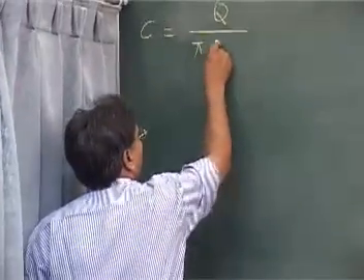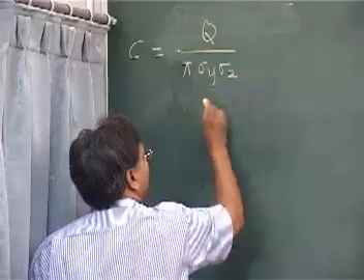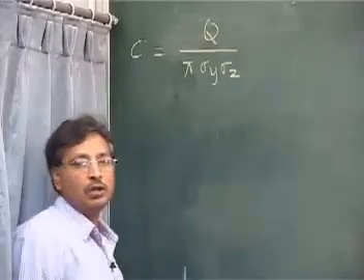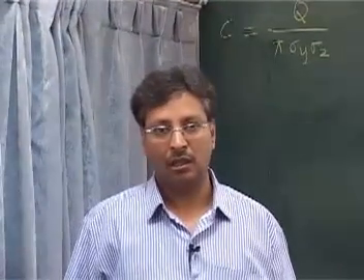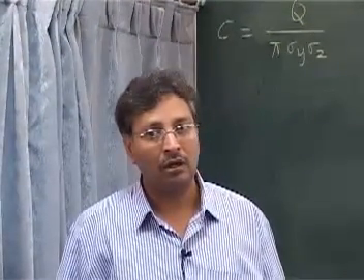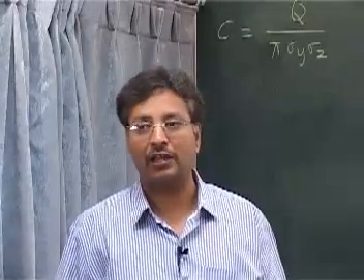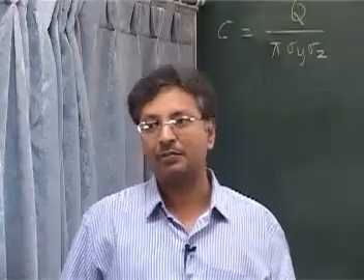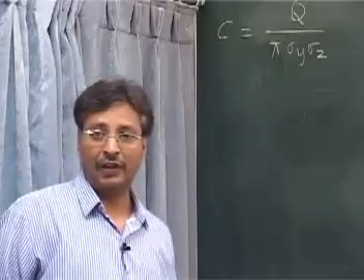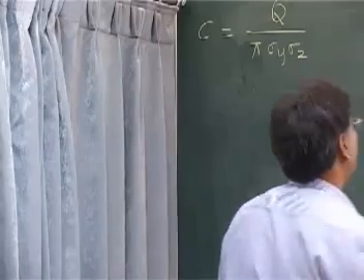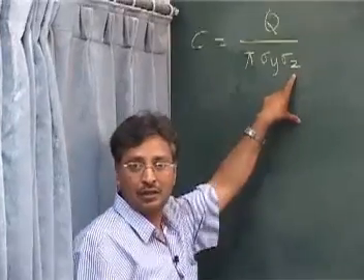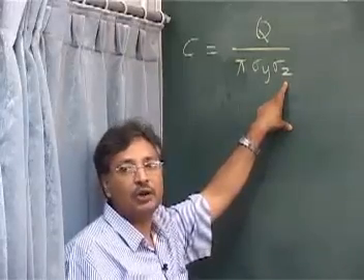Okay. So, now you say pi sigma y sigma z. Okay. Now, what u should I take at height of h plus delta h? So, height of 120 meters, right. What is my h finally? Effective stack height is 100 plus 20. So, this u will be at 120.